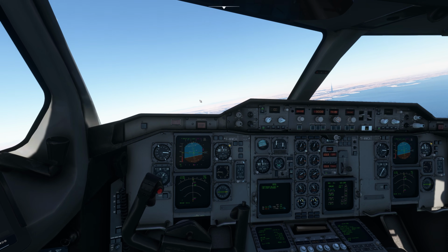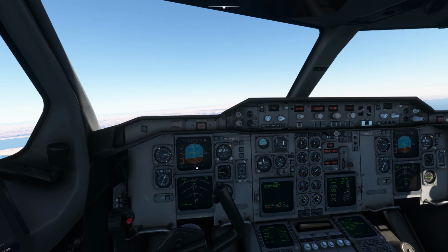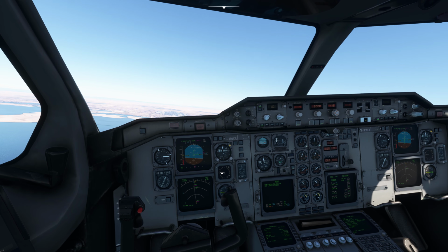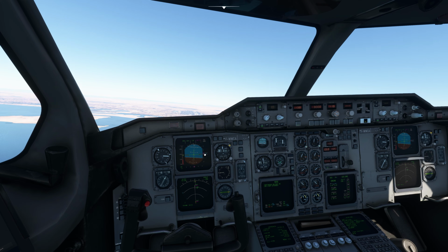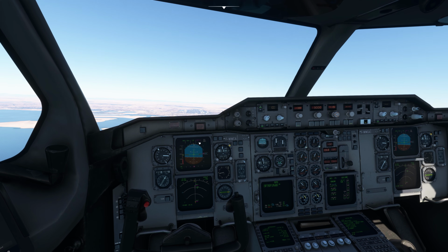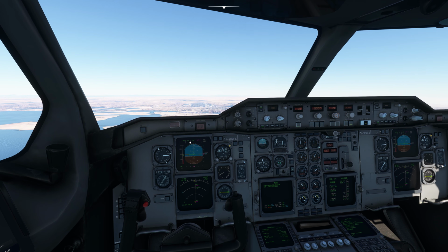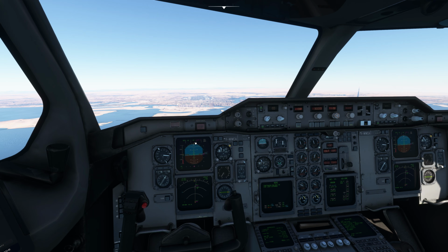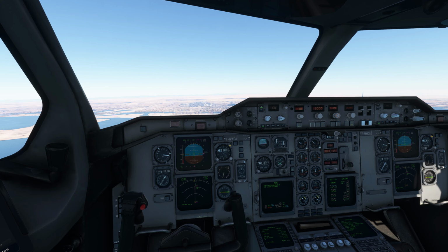Now, as soon as I've pressed the land button, you can see the plane is aligning itself with the runway. And as soon as this diamond is in the middle, you will see the vertical speed will also decrease, which means that the plane has now started its descent towards the runway. And right now, you can see localizer is locked and the plane is following the glide slope. Speed is controlled, and a category 2 landing is going to happen. If I turn on this button, you'll see category 3 coming. So it's going to be more accurate.